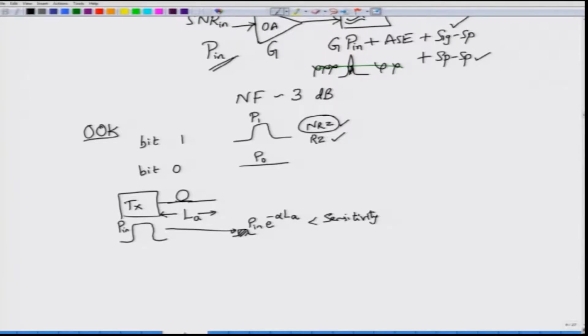So what we do here is to actually pull up the amplitude by giving an appropriate value of the gain. Okay. So you actually have an amplifier with a gain, let us call this G1. Okay. Then of course you still have one more fiber link. Let us for simplicity assume that the fiber link has the same length LA. Before you give in the amplifier of a gain G2, then you keep doing this until you come up to the last length. So here you actually have a length LA, and the amplifier that I am using will have a gain of Gn.